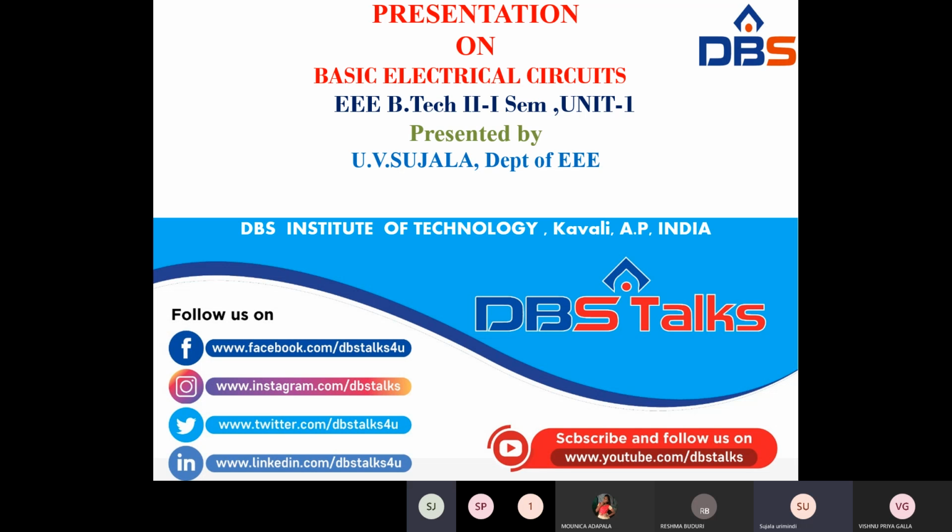It is very important. First, you have to assume how many loops are there. Second, assume the polarities depending upon the direction of the loop. And third, if there is a rise of potential, put it as a positive sign. If there is a drop of potential, put it as a negative sign. This is about Kirchhoff's voltage law.